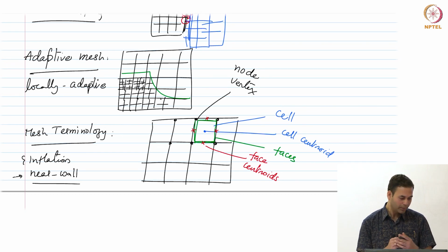and you start the simulation. Now, if I ask you to solve for a rotating vortex, okay, essentially we have a vortex which is there, or maybe a rotating flow, right. Then you would not know in which locations you would get the strong gradients. Okay. So, the location where you have to refine could come out as part of the solution. That means you need a locally refined mesh, incorporated as the solution is progressing. Okay. That could still mean an adaptive mesh.